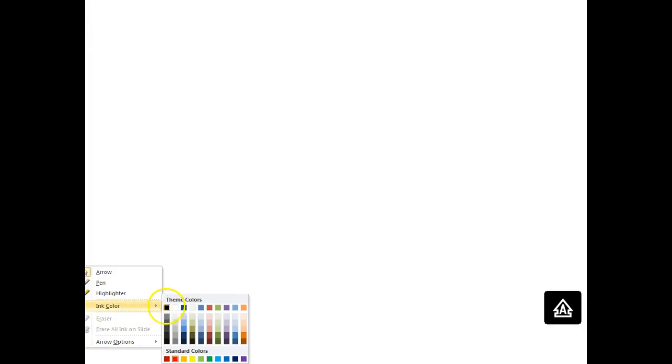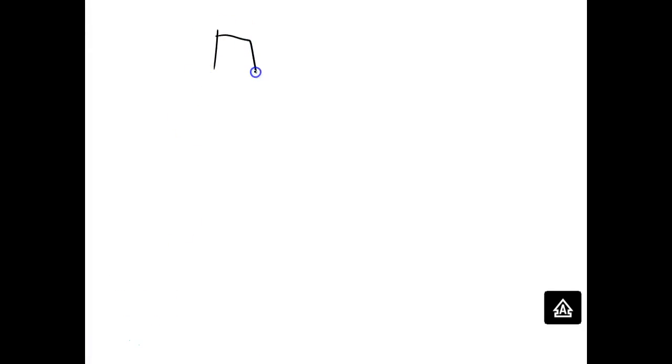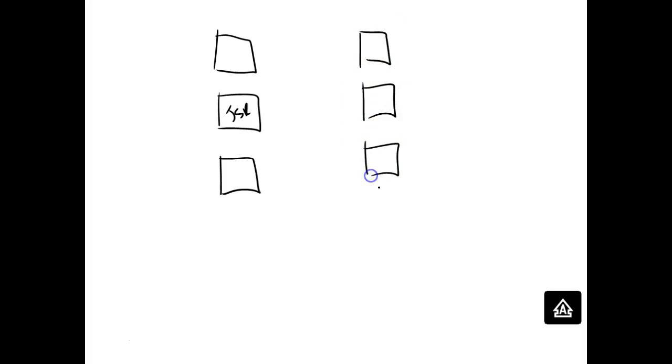So basically what we would have is a main flow, and then we might do some stuff in here, right? And down here we'll put a JSR, and then we would point it to a subroutine. This subroutine is over here, but the very last instruction is RTS, return from subroutine.